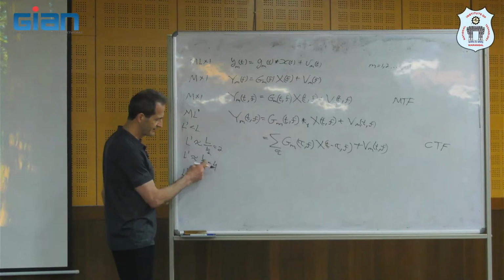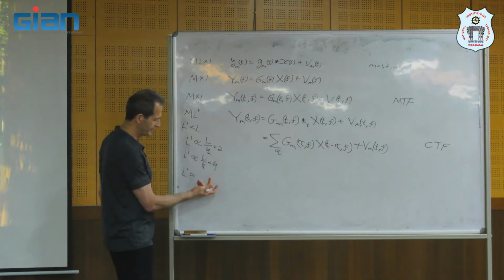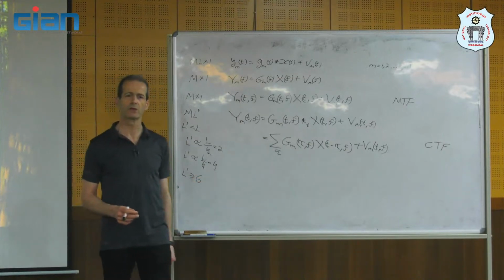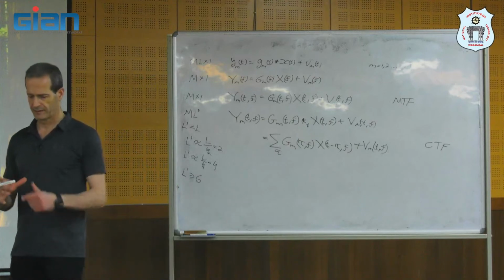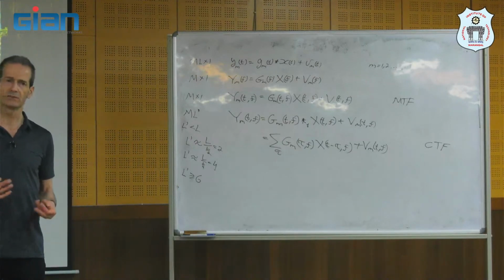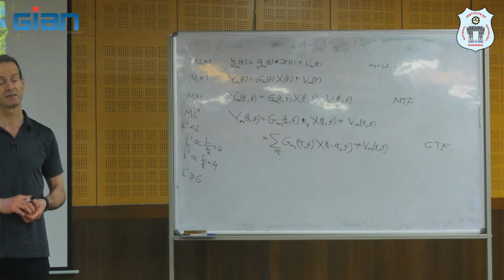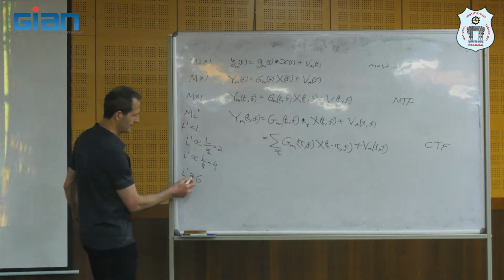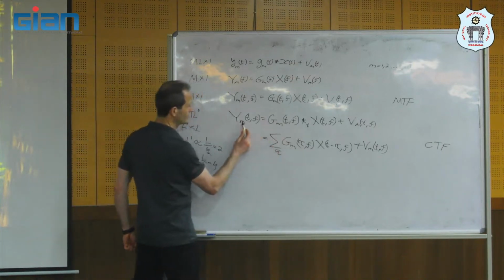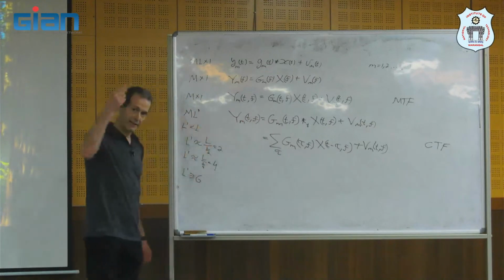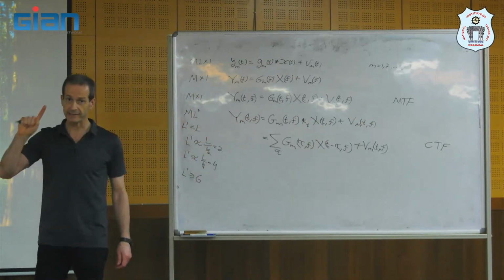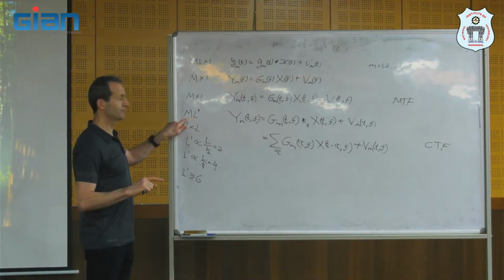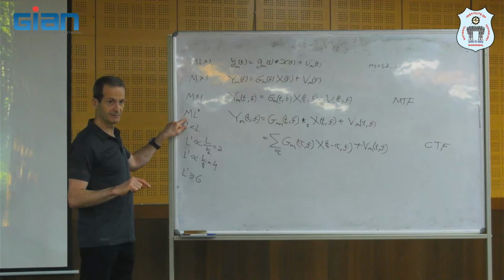If the overlap between windows in the STFT is 75%, which is a common practice, like 75% or 50%, we take like 6 windows here. So the length of the vector of measurements that we process is about 6 multiplied with M, the number of sensors.